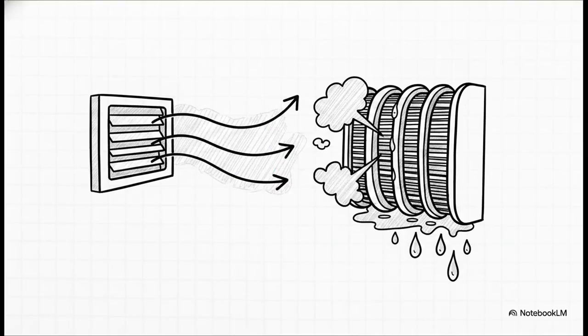But here's the catch for true human comfort. An HVAC system actually has two totally distinct jobs. First, it has to handle the sensible load. That's physically lowering the temperature of the air in the room. But equally critical is the latent load. The system has to dehumidify the space by forcing a phase change, making the invisible water vapor in your air condense into liquid on the cooling coils. If your AC only cooled the air but ignored the humidity, you'd basically be sitting in a cold swamp. No thanks. That is exactly why modern fan coils are designed with both sensible and latent cooling capabilities.